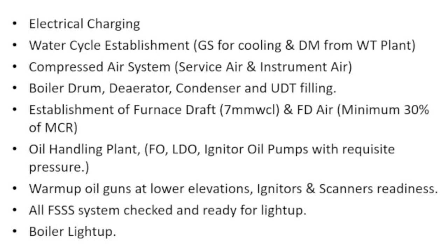Oil handling plant, this has to be also ensured. FO, LDO, igniter oil pumps with requisite pressure. Warm up oil guns at lower elevations, it means AB, CD, igniters and scanners, their readiness also to be checked. All FSSS system should be checked and ready for light up, and then the next sequence will be boiler light up.